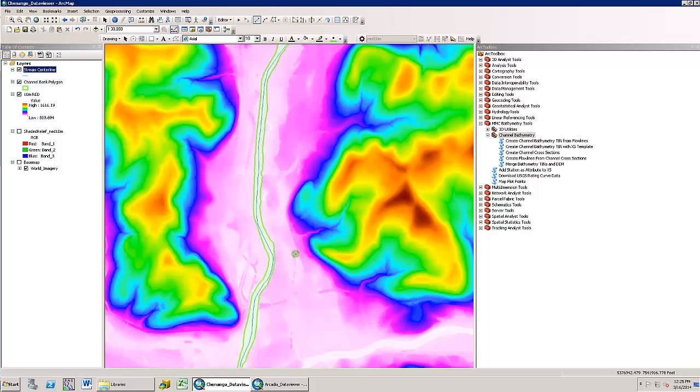It can be 2D or 3D. This tool will only work for one stream source. It will not handle streamline features that represent tributaries. It will work if the features represent one stream source and the line is split into different reaches, as long as they are connected and can be merged into one feature without creating a multipart.